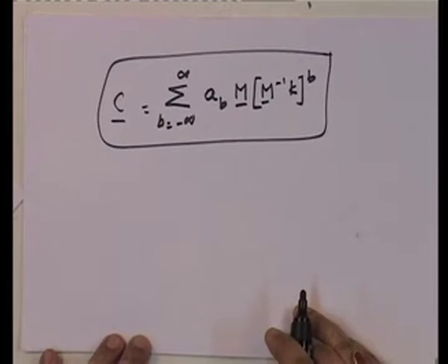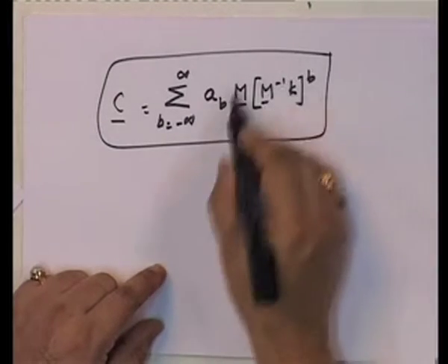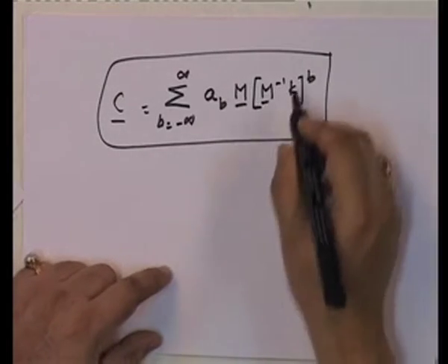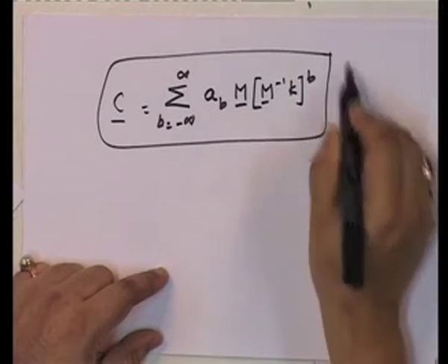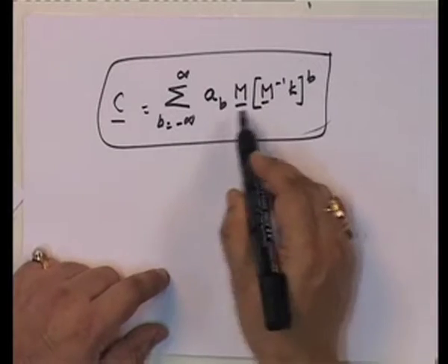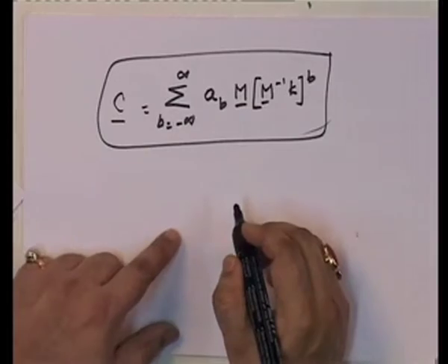If C is of this form, it is also proportional, because we have shown that this is proportional. In other words, the orthogonality condition of this we have shown. So, if it is a linear combination of all of these, automatically C is also orthogonal. I mean, the mode shape vectors are orthogonal with respect to the C matrix. So, let us look at what happens.